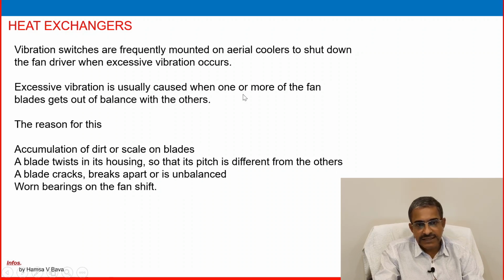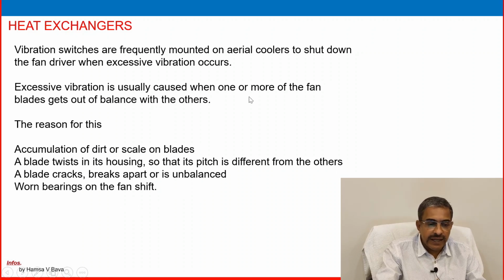These are the conditions where vibration increases, and vibration switches are provided as a safeguard to shut down or trip the motor on high vibration. That is also a safeguard on aerial coolers or fin fan coolers.